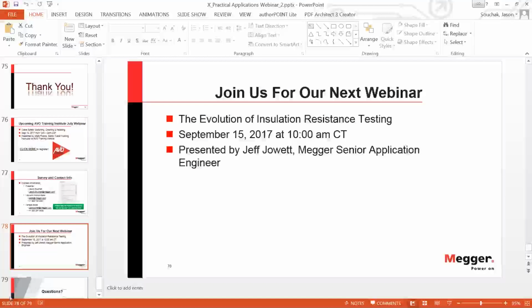First question is for our panelist Henning: for which defects is DC testing blind? Typically you can say DC testing finds resistive type defects fairly well, but not defects that are more capacitive type defects, like you would find in splices and terminations.